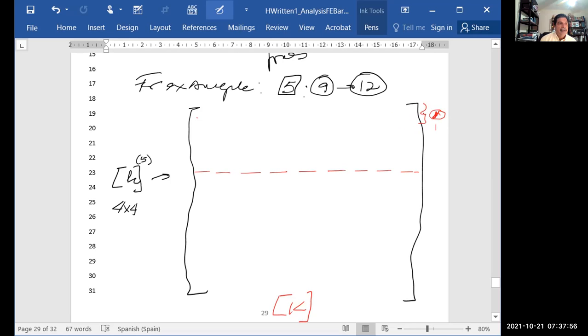No. Every joint has 2 degrees of freedom in X and in Y. So for joint one, I have F1X, F1Y, etc. Then I go for joint 2, 3, and 4. So Mr. Ordóñez, tell me, in what row are you going to include the first row of this local stiffness, and I'm sorry, the element stiffness matrix?